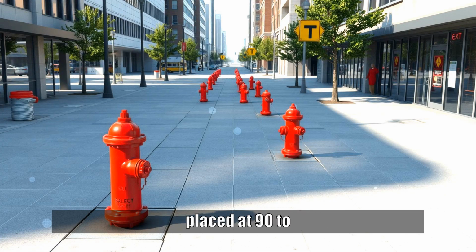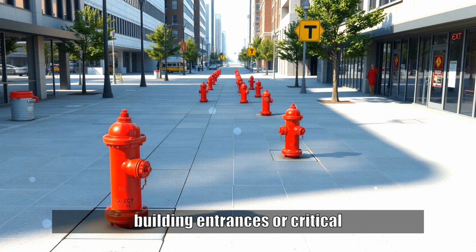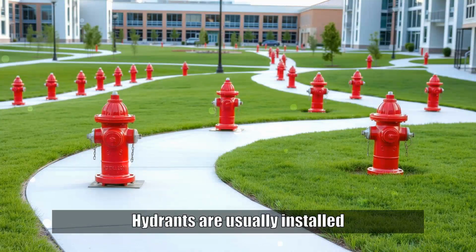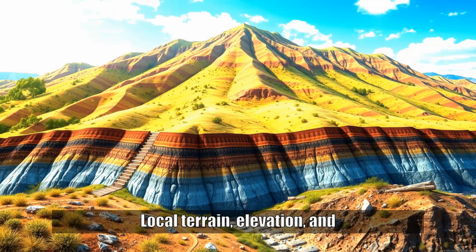Typically, hydrants should be placed at 90 to 120 meter intervals in commercial or industrial zones and within 30 meters of building entrances or critical infrastructure. They must be accessible to fire trucks, not obstructed by parked vehicles or landscaping. Hydrants are usually installed along roadways, but in campus-style layouts or large complexes, they may be positioned along internal fire lanes or dedicated hydrant lines. Local terrain, elevation, and accessibility in all seasons must also be considered.